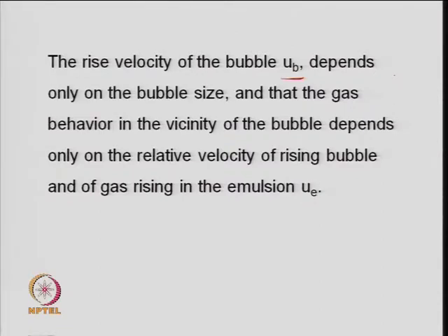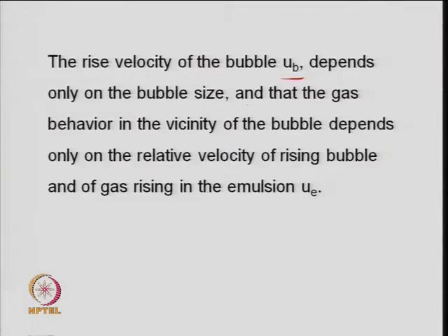In the bed, the velocity at which the bubble is going up matters, because the residence time of the gas bubble is important, and for how much time that gas bubble is in contact with the solid will decide the conversion or average conversion. The gas behavior in the vicinity of the bubble depends on the relative velocity of the rising bubble and the gas rising in the emulsion. So, gas is in the emulsion phase, gas is in the bubble phase. Let us see that.